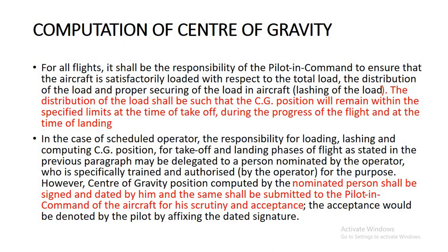During each flight, the pilot is responsible for making sure that your loading is perfect and within the CG range, and all loads are tied and secured. It will not move during flight, so it is the responsibility of the pilot in command. Sometimes in organizations like airlines, there is a person who does the load and trim sheet calculation. He will calculate it and give it to the pilot in command. He will accept it and agree by making his signature. Then he can take off the aircraft.